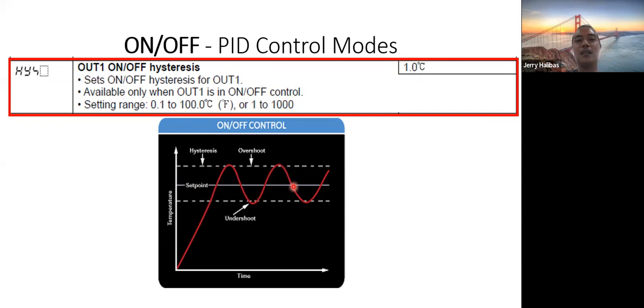It goes up and down around the dead band. So if you change this to something very small, it switches faster, it goes up and down quickly. For example 0.01 or something, with very small changes in temperature it will start pulsating up and down.